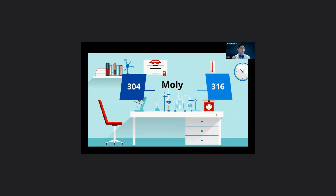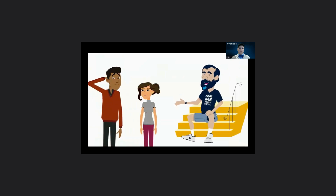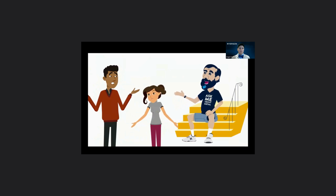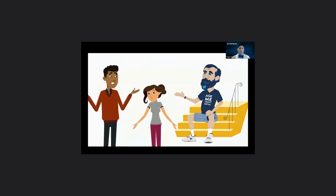316 is in the austenitic family of stainless. It contains anywhere from 2 to 7% of moly, which is higher than that contained in 304. The higher the moly, the higher the corrosion resistance. You know, moly is what they call a ferrite former. That means that when it's added to improve the corrosion resistance of an austenitic stainless steel, there must be an austenite former such as nickel or nitrogen that is added in order to keep the structure austenitic.